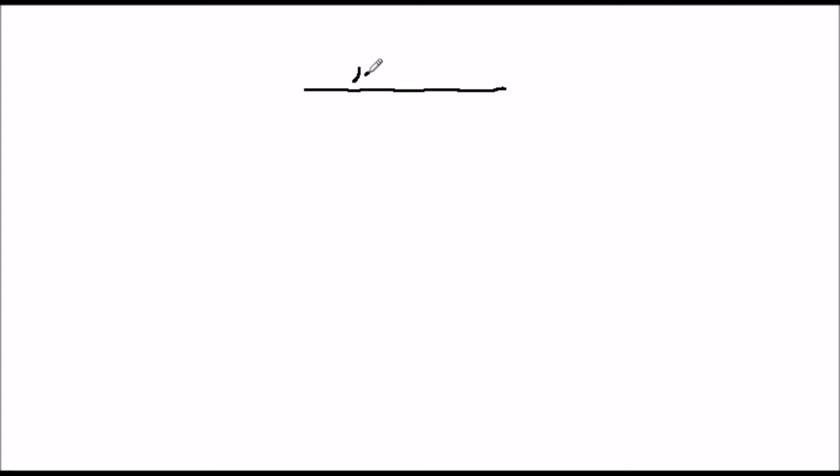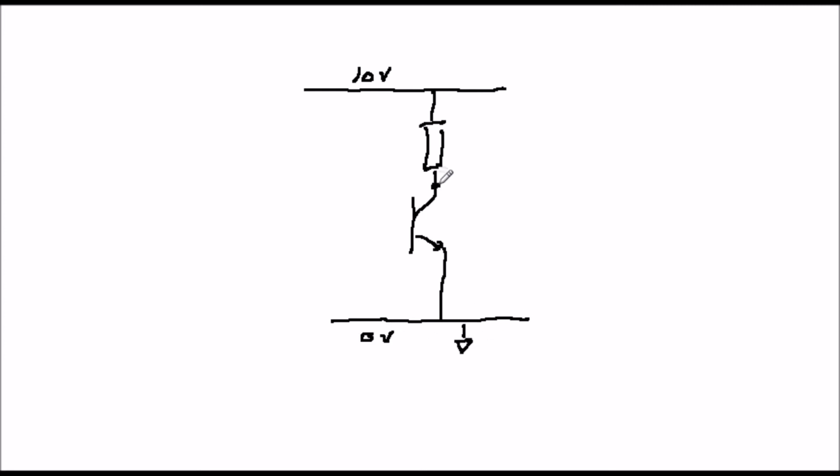In practical circuits, it's also necessary to put in a couple of capacitors. The purpose of these is to allow the AC signal which we want to get into and out of the circuit, but to stop the DC bias voltages which we've set up from escaping from the circuit. That is the 5 volts on Vout and the 0.6 volts on Vin. If you're unsure about the role of capacitors in this circumstance, then review video 14.